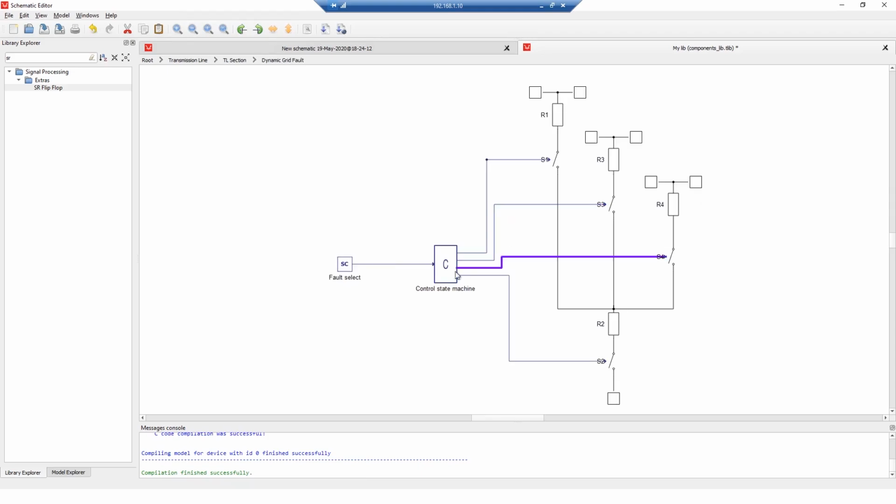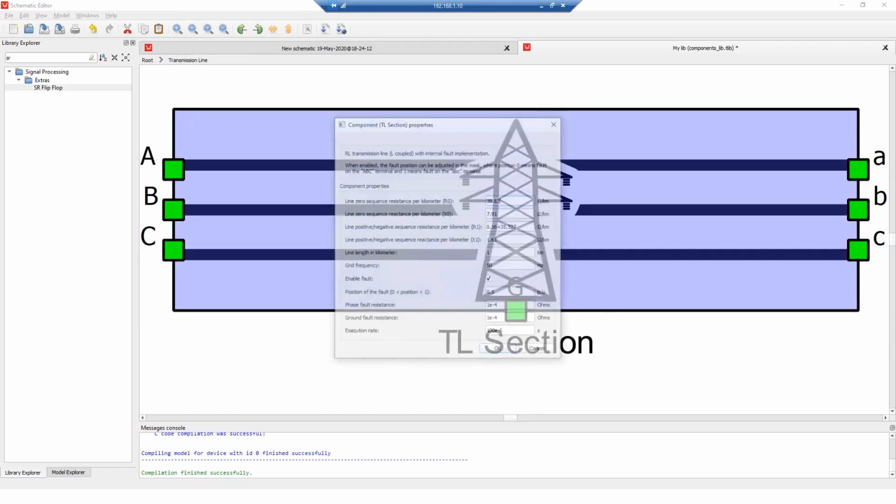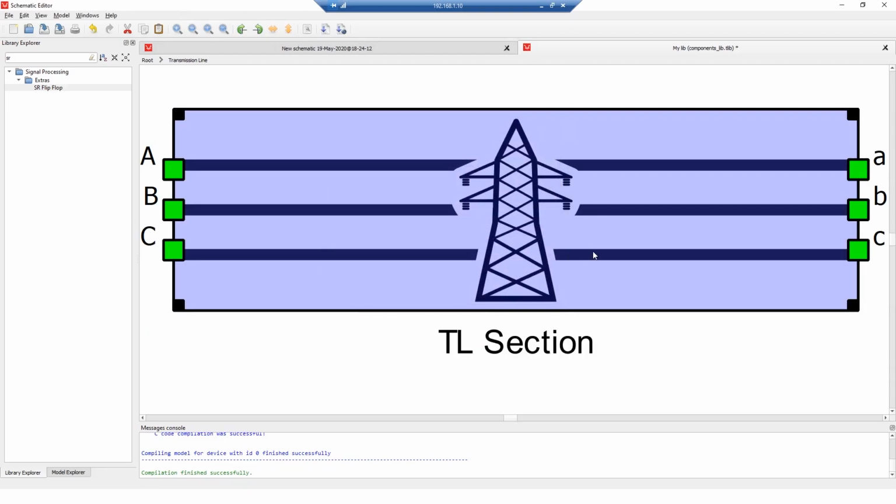This component actually uses 4 switches to combine them and cause all types of short circuits that we'd like: phase to phase to neutral, single phase to neutral or to ground. So we can do everything here, and notice that it's much easier to parameterize. If I uncheck and press OK, of course, then I remove that fault and extra transmission line.